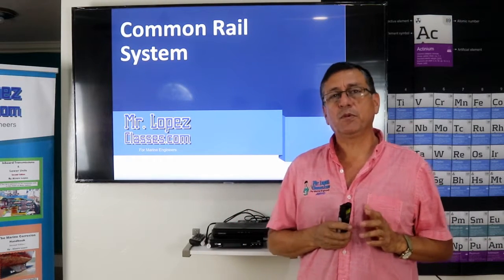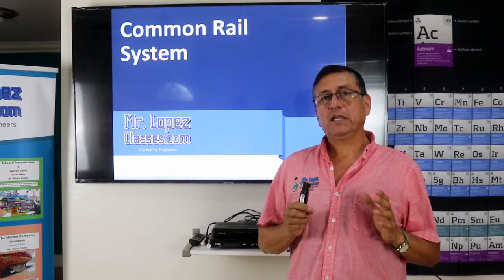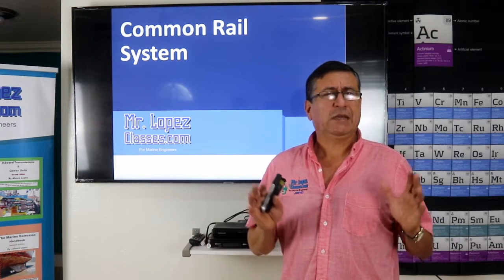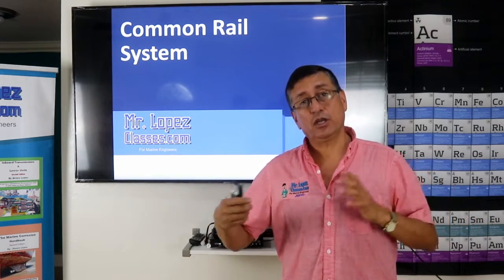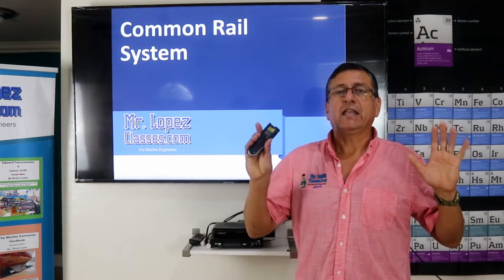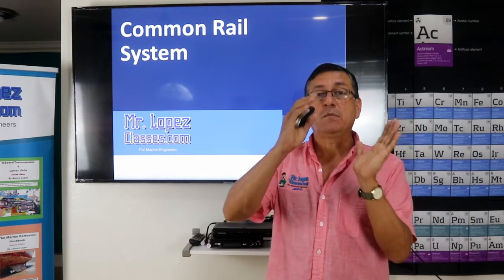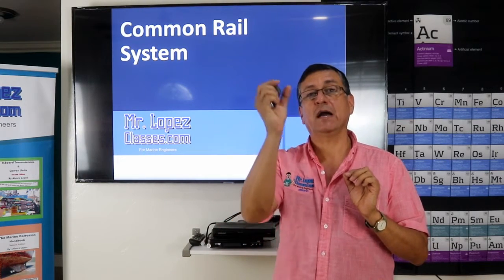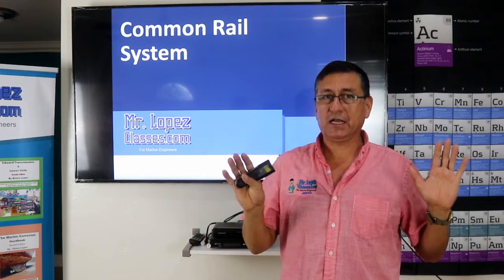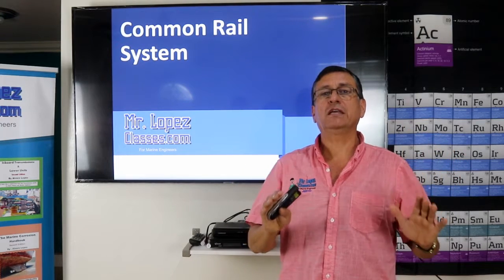If you remember in the previous episode, I explained the different types of pumps. Basically they are mechanical fuel injection pumps or electronic fuel injection pumps. The mechanical fuel injection pump should be timed according to the position of the camshaft and crankshaft. For a mechanical fuel injection pump, it is mandatory, it is necessary.